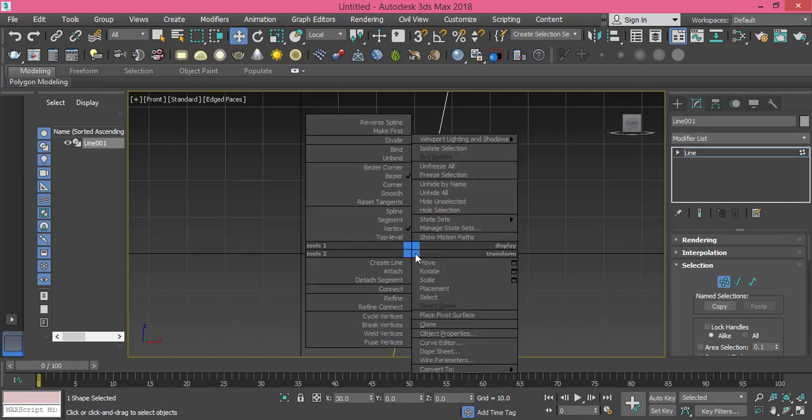So right click to see what types are available for vertices. We have 4 types. We have the smooth. I don't use it and I don't recommend using it. It's suitable for splines that have too many points, but it doesn't give you full control of everything. Corner, and I will pick it for this one. It's suitable for having sharp corners like beginning or endings.